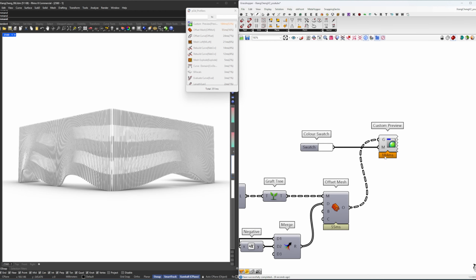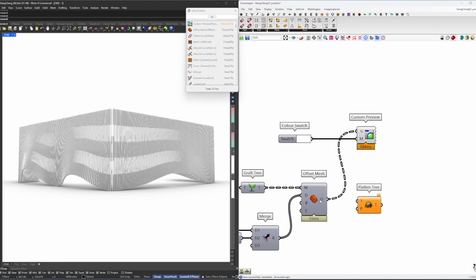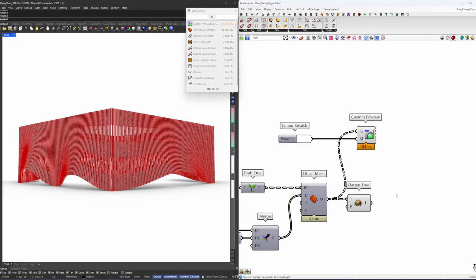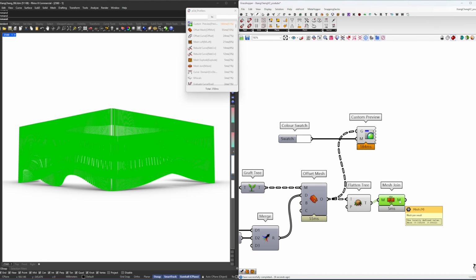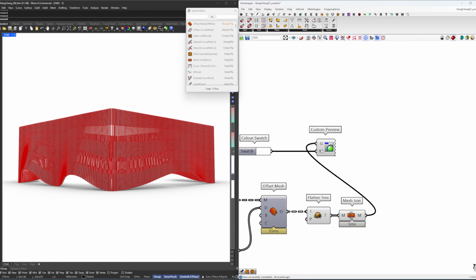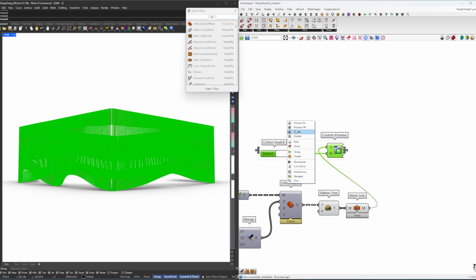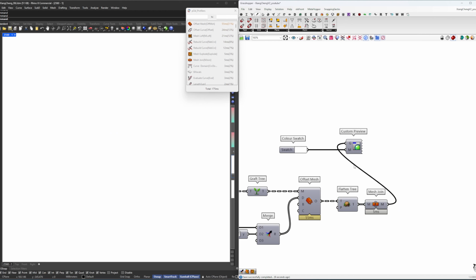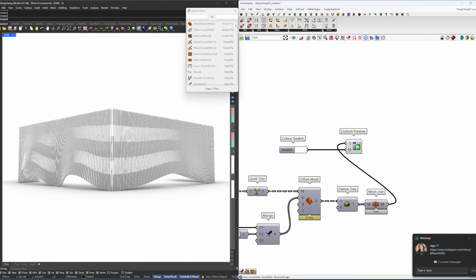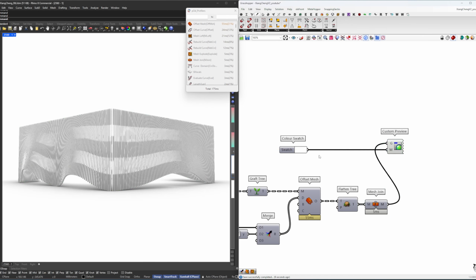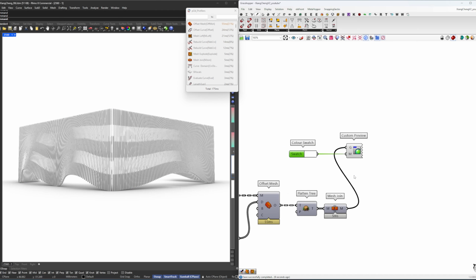You do see that this takes relatively a lot of time, 184. What is always good to do with the mesh is a nice component called mesh join. Just join the whole mesh into one. It will create a lot of mesh faces, but if you put this in here, you see how much faster it actually is. Let's hide all this and show just this one. And now we are still at 175 milliseconds, which is absolutely nothing.